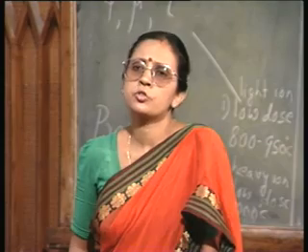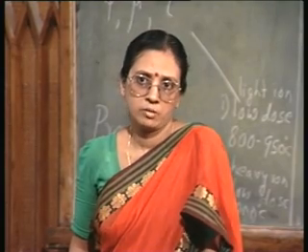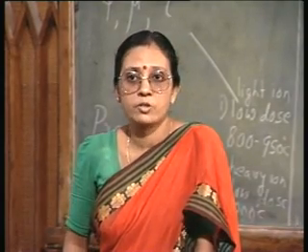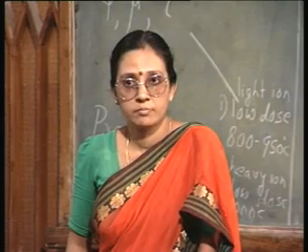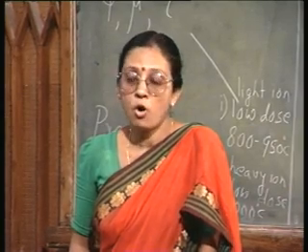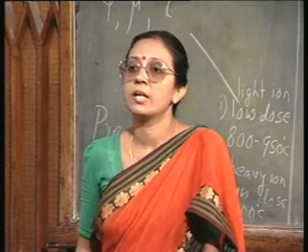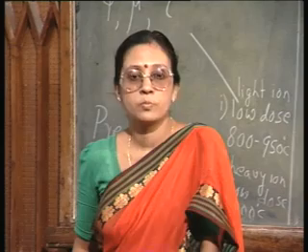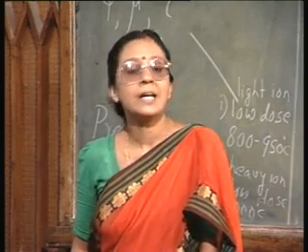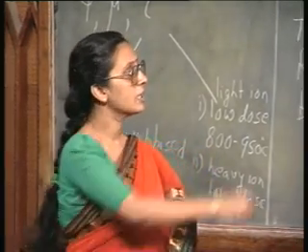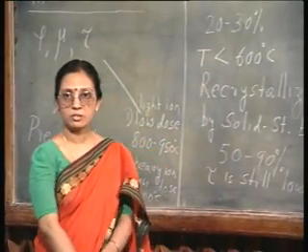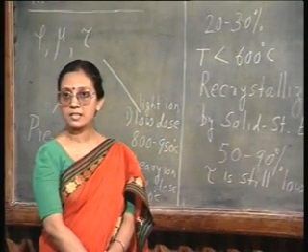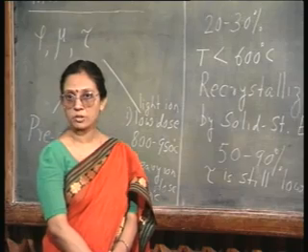Either I have put a very heavy dose of a heavy ion like phosphorus, which will cause pre-amorphization, or prior to the implantation itself I have done some self implantation which has caused the layer to be pre-amorphized. But there you see it is much easier to get back the carrier activation. By 600 degree centigrade I can get back the carrier activation.